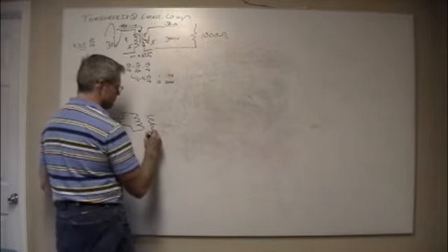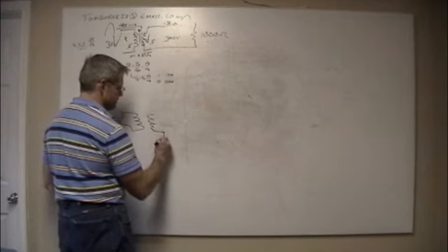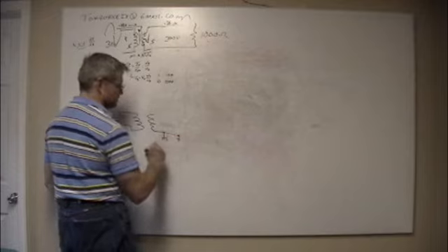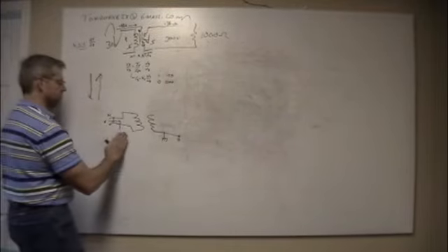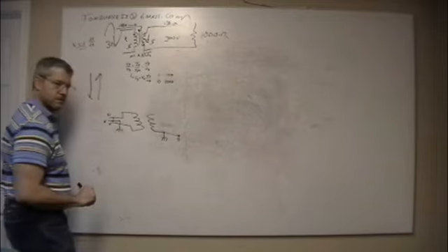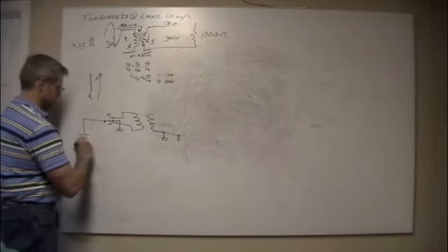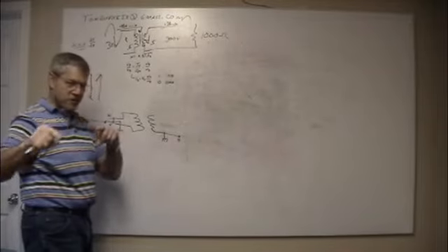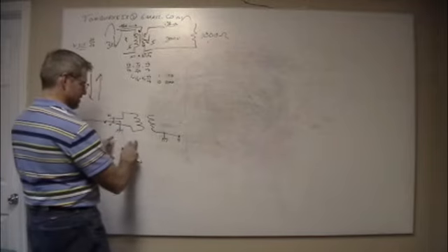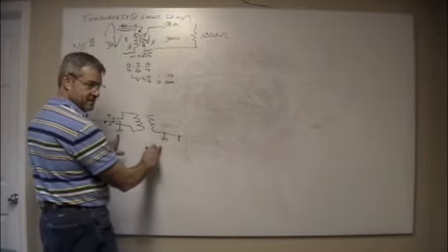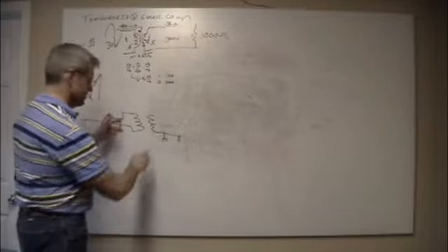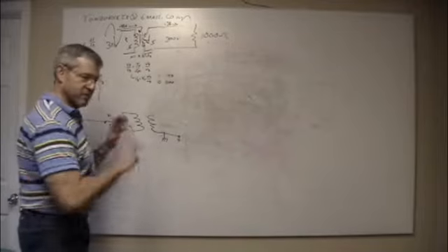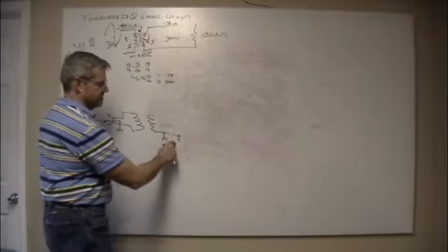But what you'll do for a DC power supply is you'll tie this to chassis, and this becomes your reference ground also. And then out here it comes to earth. So now I've got ground's a ground, the whole world ground. Ground is ground. But these symbols represent that it's a chassis, that it's tied to the outside of the box. So if something shorts out and blows up, it's going to go to ground before it goes to you. Okay, yep. Protection. But now I say this is my signal ground.